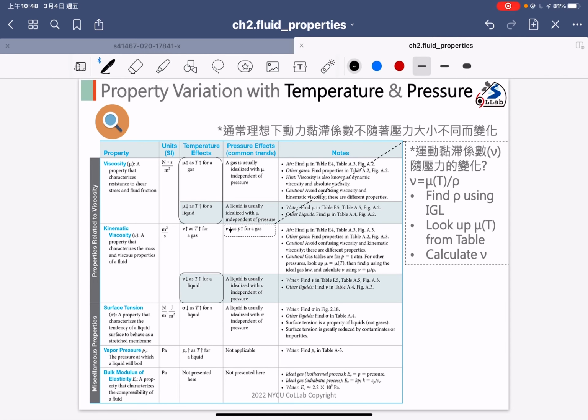this is very difficult, so you need to wake up here. So you see the viscosity mu. Okay, for the gas, when the temperature increases, the mu also increases. Mu is viscosity. The reason why, for the gas, the viscosity increases with temperature is that in the gas there is no certain interaction force between two gas molecules.